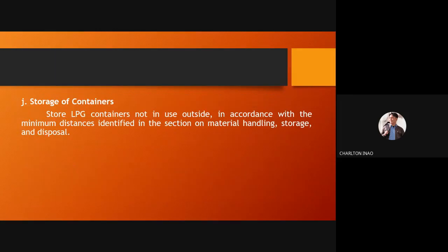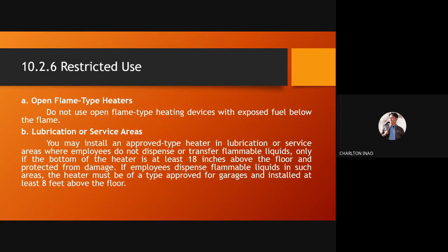Containers. Store LPG containers not in use outside in accordance with the minimum distances identified in the section on material handling, storage, and disposal. Restricted use. For open flame type heaters, do not use open flame type heating devices.